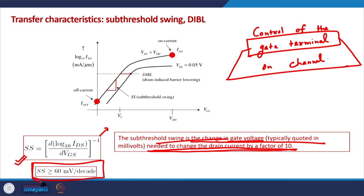For a MOSFET, the subthreshold swing is always greater than or equal to 60 millivolt per decade. 60 millivolt means that at least a 60 millivolt change in the gate voltage is required in order to change the drain current by a factor of 10 in the subthreshold regime of the transistor.